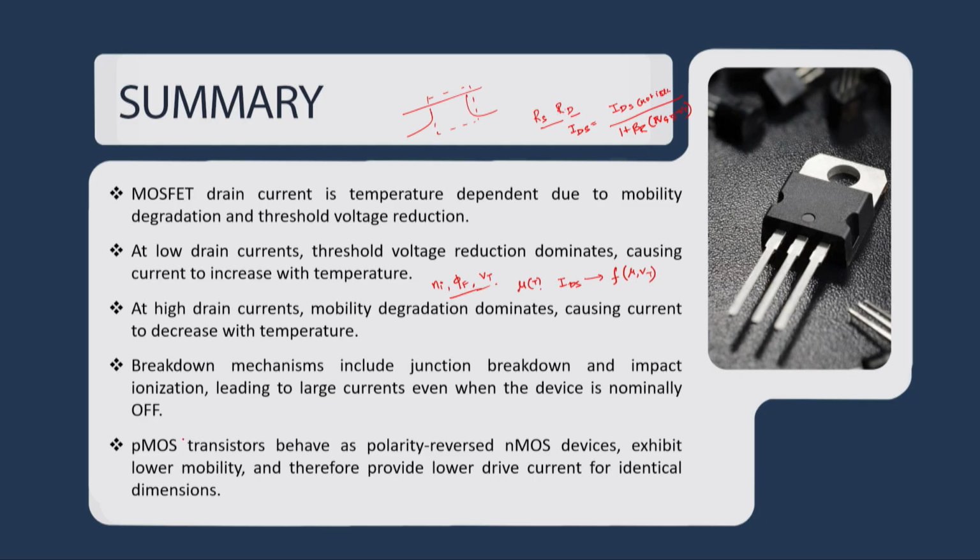At last, we have seen another flavor of MOS transistor, which is called the PMOS transistor, which we can define in one statement as a polarity flipped transistor of the NMOS device, where the polarities of terminal voltage and current get flipped, and all the inherent physics that we have discussed in terms of depletion, inversion, weak inversion, etc. will be applicable for the PMOS transistor similarly to what we discussed for the NMOS transistor.